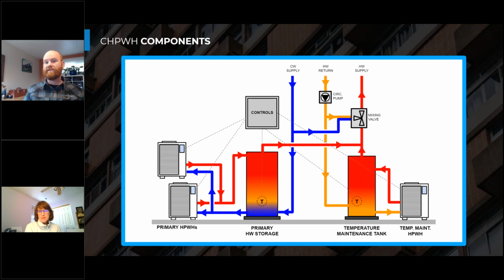It's available, electricity is readily available on the grid, but we have to essentially use it when we make it or generate it. Heat pump water heaters are really well suited to basically load shift because we have these thermal batteries. So we can align the time of use the heat pump water heater runs with the time of available solar energy on the grid. And that can dramatically reduce the cost of energy, because in places like California, we have time of use pricing. Basically, electricity varies in price depending on the time of the day.